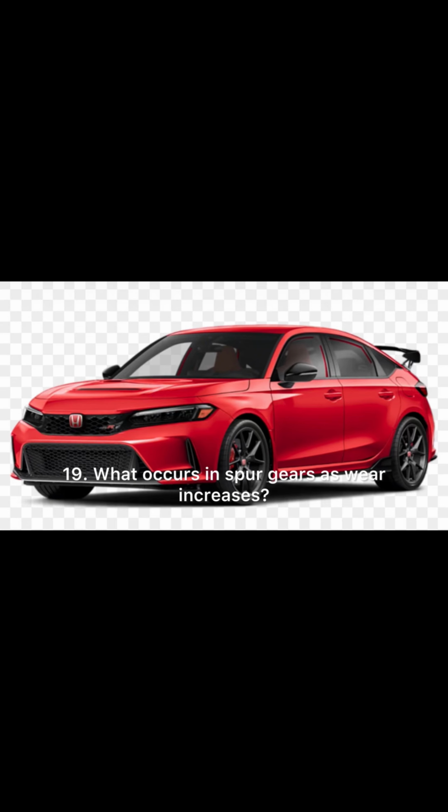23. In manual transmissions, what two components are used to control end thrust? Thrust washers and snap rings. 24. What does the gear ratio comparison mean when expressed to 1? The amount of drive gear revolution required to make the output gear rotate 1 complete revolution.